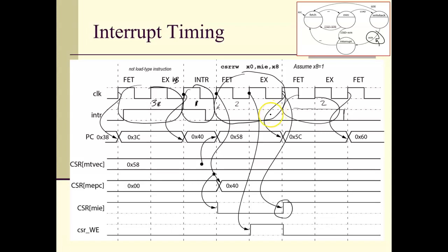If it's longer than 8 clock cycles, there's a chance it may execute the same interrupt service routine again. So once again, worst case, 3 clock cycles, roughly speaking, for a load type instruction, 1 clock cycle for the interrupt cycle, 2 clock cycles for the instruction that re-enables the interrupts, and then I want it gone by the end of the next instruction, which could be any instruction, but I want it gone before it completes the execute cycle. So the answer essentially is 8.